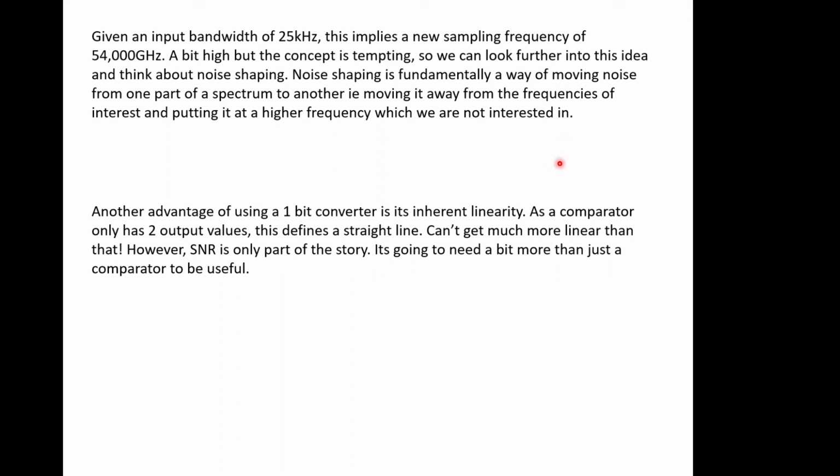So that's an interesting concept. So hold that idea that we're going to move noise from one end of a frequency spectrum to the other end. So the average noise is still the same. We haven't done anything particularly magical, we've just moved it somewhere else. And then as long as we can filter that bit away, which we can do because we'll have separated the signal from the noise, we can improve the signal to noise ratio, only for digital signals.